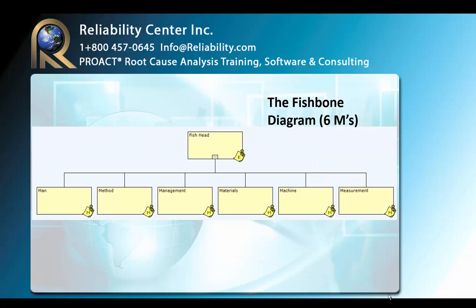Another common method is the Fishbone Diagram. In this particular one, we're looking at the 6 M's. And the way we have our diagram positioned, our fish is oriented swimming upstream. The fish head would represent the problem statement. And then we have man, method, management, materials, machine, and measurement. And we would explore any or all of those categories to see where we may have had a weakness or a failure may have occurred.